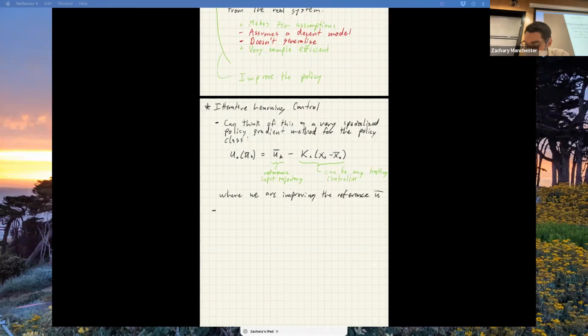Another way to think about it is as an SQP method, like a direct trajectory optimization method, where we're evaluating the right-hand side vector when we solve the KKT system on the real system. We can compute the whole matrix using our approximate models, all those Jacobians, Hessians, whatever, coming from our nominal model. Yeah. Could you clarify again what the letters and subscripts on the left-hand side of the equation mean?